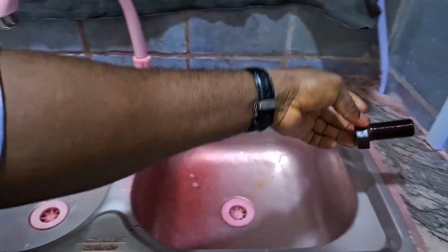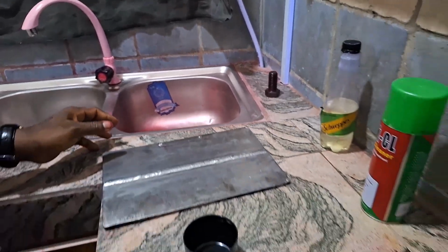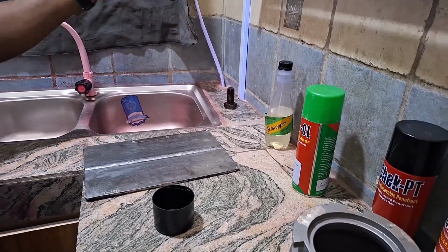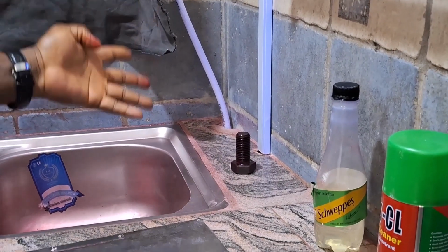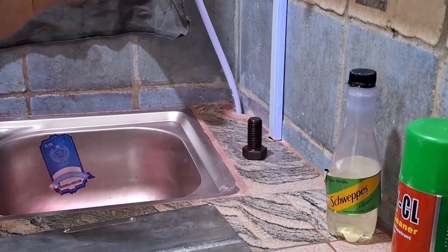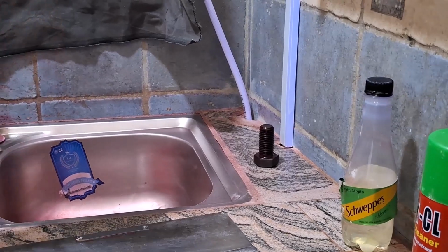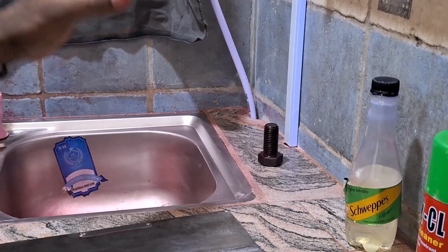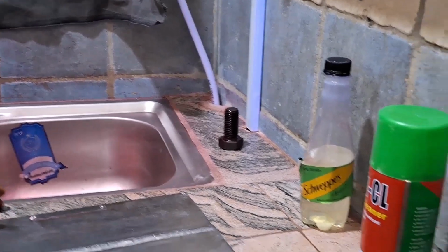When you are performing your test, you definitely leave it for some time to allow it to dwell. Dwell time is dependent on a lot of factors like material type, the temperature, the thickness, and all that. But usually it's between 5 to 15 minutes, depending on what the procedure states or what the standard states. So as the inspector, you need to know the dwell time you are using.